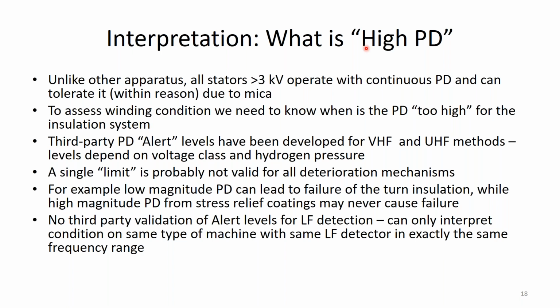Okay, I also need to point out for the low frequency detection system, whether it's ours or others, I have seen no third-party validated tables for what are high levels of PD. I know there's lots of vendors who give out numbers, but they're suspicious right off the bat because they don't depend on hydrogen pressure, they don't depend on voltage, they don't even really depend on the sensor they use, it seems sometimes. So they're a little suspicious from that point of view, but in fact, other people have not been able to independently validate those levels. And there's good, strong reasons for that. I encourage you to read the IEC and IEEE standards I talked about before, okay?